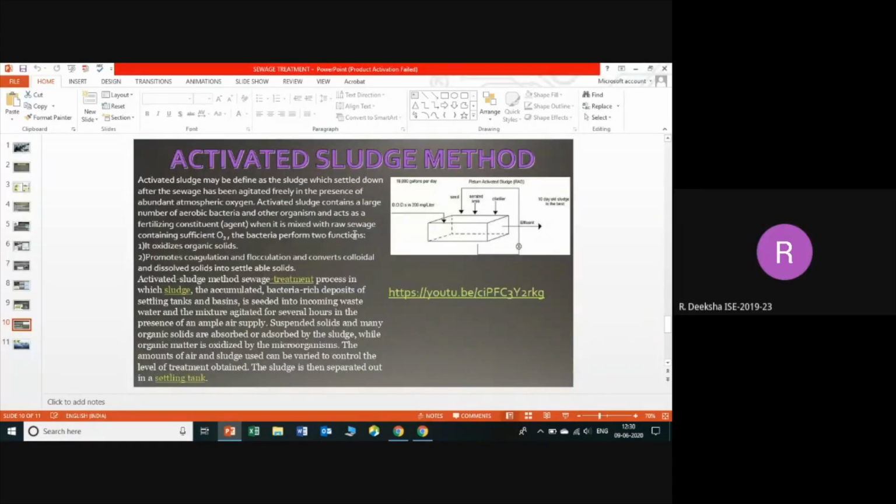Activated sludge method. Activated sludge is defined as the sludge which settles down after the sewage has been aerated freely in the presence of abundant atmospheric oxygen. Activated sludge contains a large number of aerobic bacteria and other organisms and acts as a fertilizing constituent when it is mixed with raw sewage containing sufficient oxygen. So it performs two functions mainly. It oxidizes the organic solids, then it promotes coagulation and flocculation and converts colloidal and dissolved solids into settlable solids.